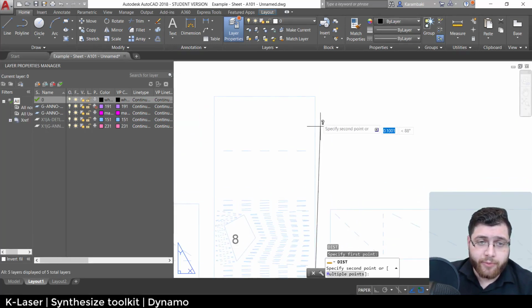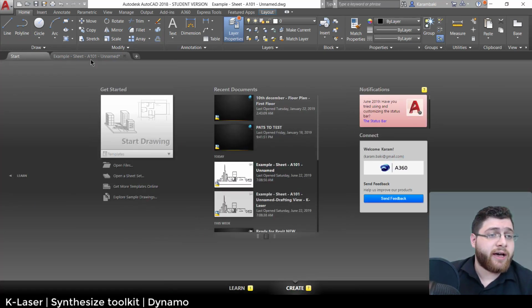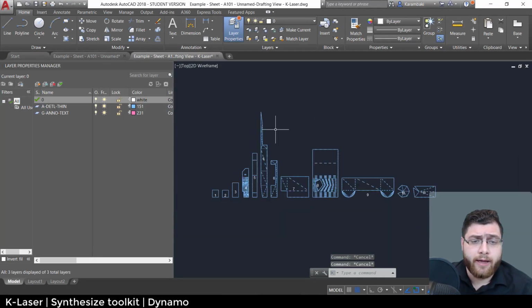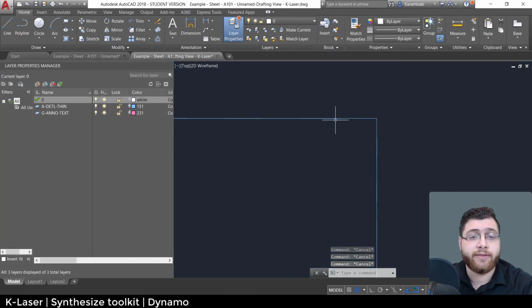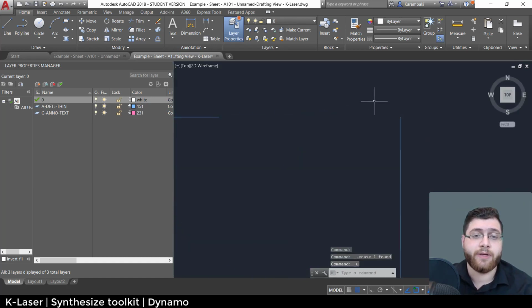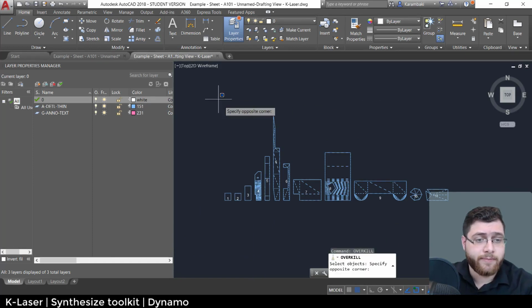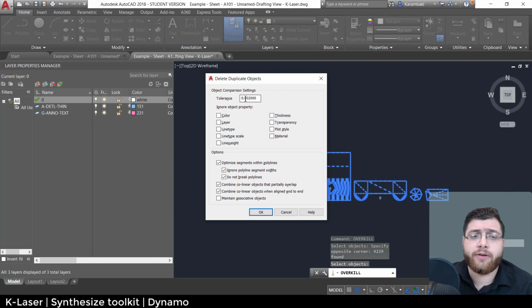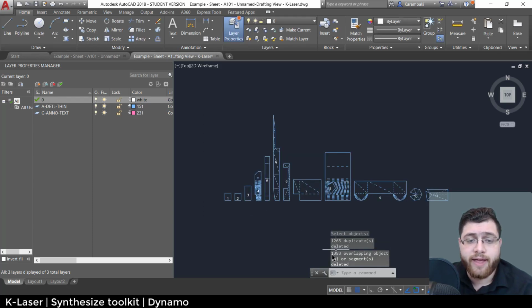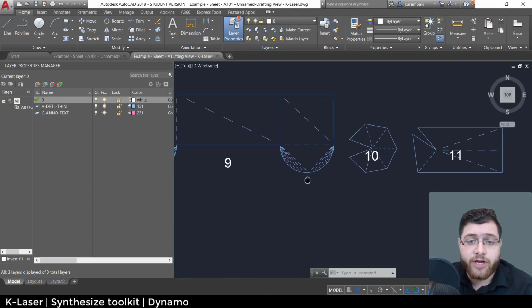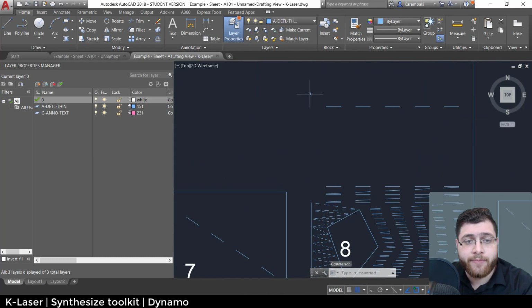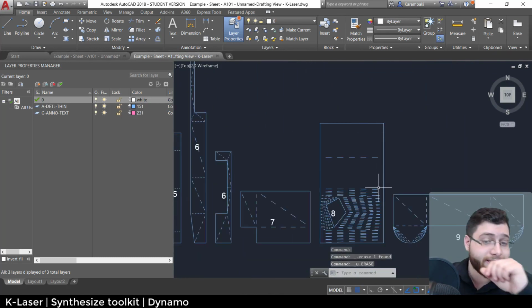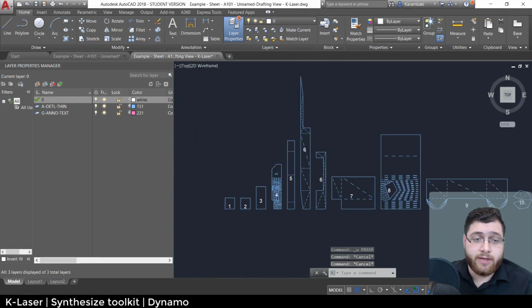With my limited knowledge of AutoCAD, when I start to laser cut this, I open the same drawing and directly do an overkill, which is highly important, because if you don't do an overkill, you will see that dozens of lines are above each other, as you can see. So I'm going to try an overkill. The settings of overkill are pretty straightforward. Just increase the tolerance to the level you are satisfied with. I am satisfied with 0.02, so I'm going to click OK. It killed 1,383 lines. If you check, you will see that there's no loss of information, and if you check more, you will see that when you delete a line, there's nothing behind or below it. That means it's completely clean. Of course, it depends on your preferences.